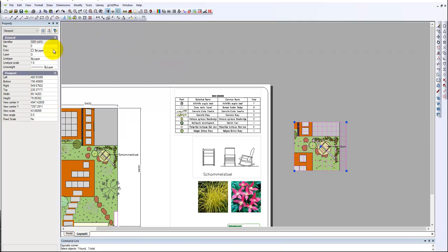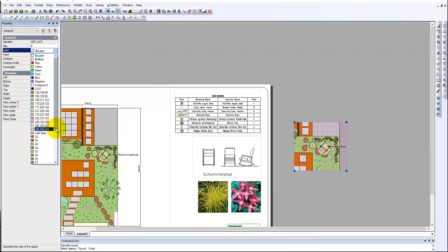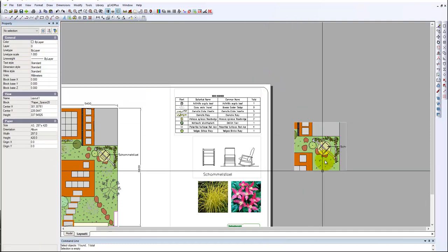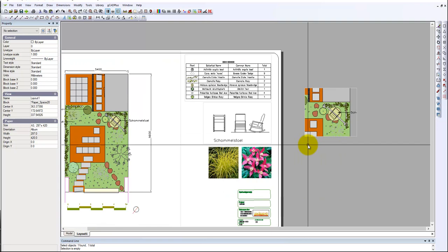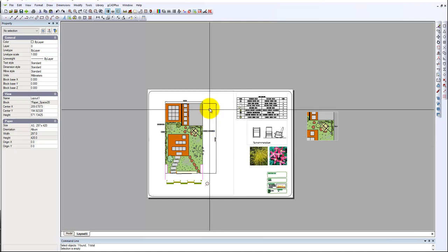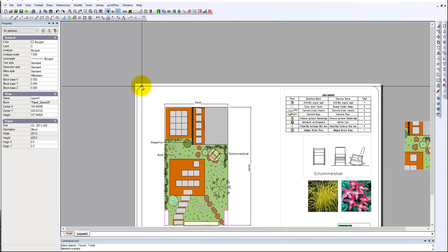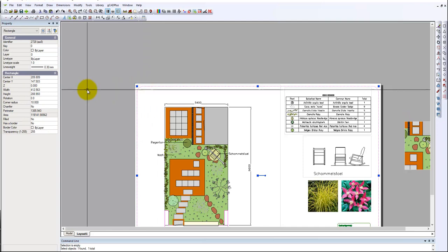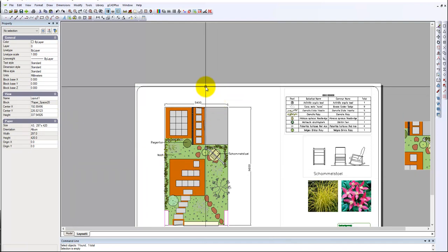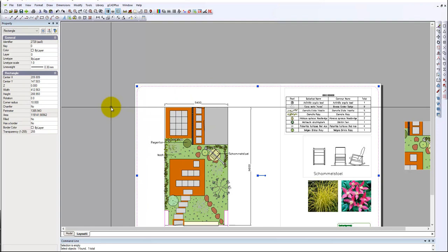I changed the colour, you might have noticed, to 254 so it doesn't dominate. So we can have a floating viewport to look at any part of the design. When it comes time to print this, the other thing I've done is to put a rectangle with a corner radius of 10 millimeters around the edge, and I've made a thickness of 0.3.